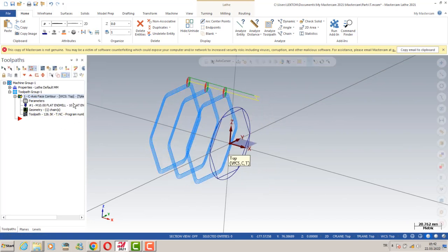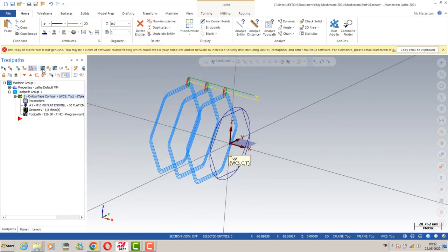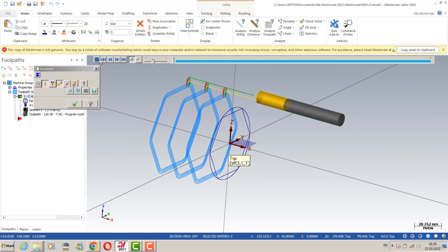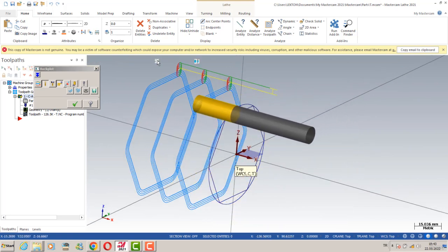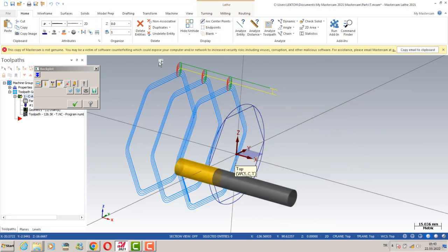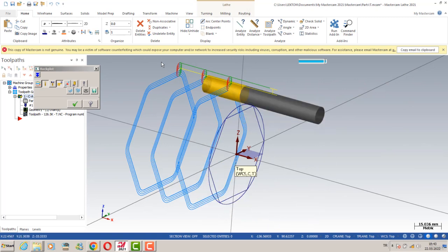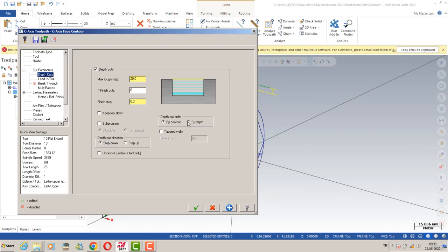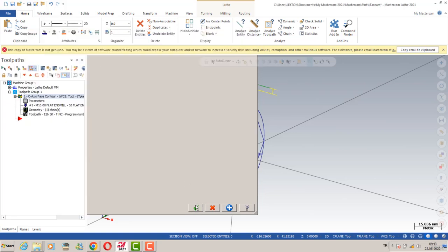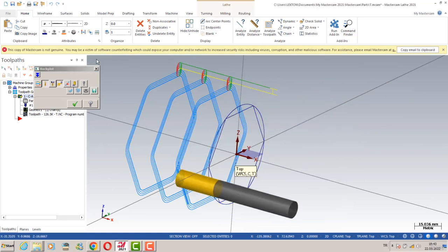Okay, this is the multi-axis options in our process. So we can use the by contour options, and the by contour option is gonna be like this. We're gonna focus on that contour first, like this, and then we can create finished multi passes, and then we can go to the another depth of cut, and then we can repeat that process again and again. If you click by depth here, not by contour, and then recalculate it, we're gonna see that kind of options.